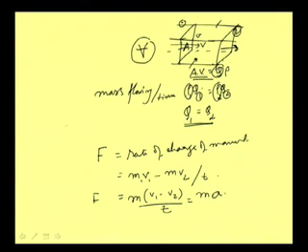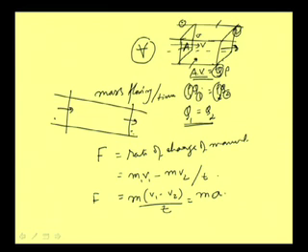Then the third basic principle is conservation of energy. Again here, suppose we consider energy at an upstream section and energy at a downstream section, where will the energy be more? Definitely, when a flow is moving from upstream to downstream, the energy level at upstream must be more than the energy level at downstream. That is why the flow is moving in this direction.